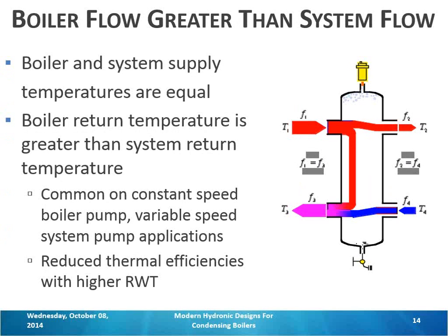In the majority of the year, we're operating in part load condition. So this pump is, if it's a 3-to-1 or 4-to-1 turn down pump, it's bottomed out the majority of the year. So you have multiple boilers probably running at low fire. Their pumps are providing full flow, but the system pump is turned down. And the effect you get is you're pulling that hot water that the boilers are supplying right back in to the boiler's return connection.